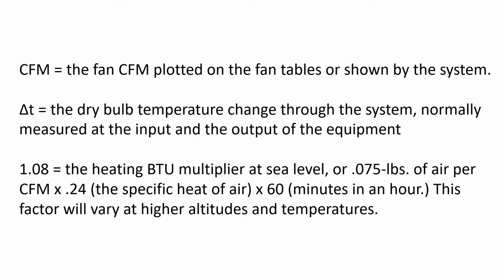Again, the CFM is the CFM plotted on the fan tables or shown by your system display. The delta T being the dry bulb temperature change through the system, normally measured at the input and the output of the equipment. The 1.08, our heating BTU multiplier at sea level, is the specific heat of our air over our CFM 0.24 times our 60 minutes in an hour. This factor will vary at higher altitudes and temperatures.